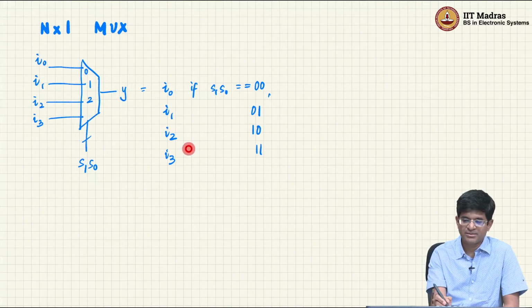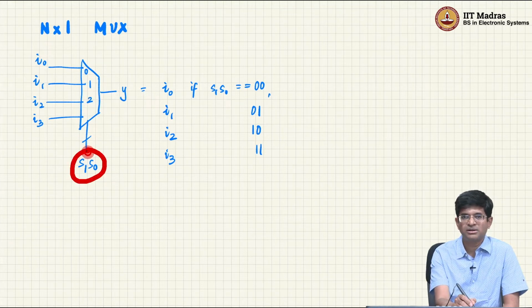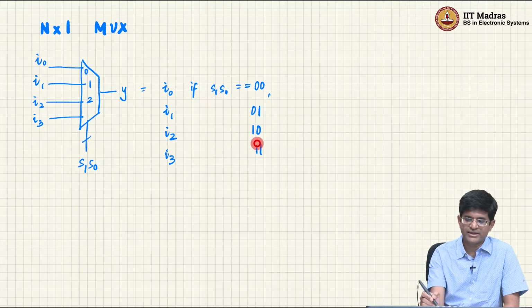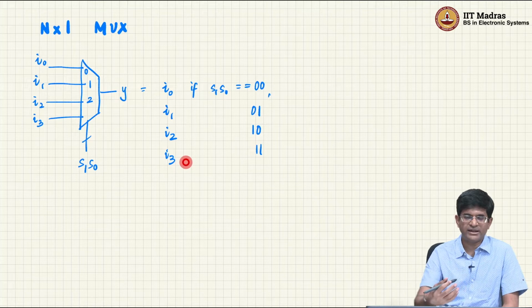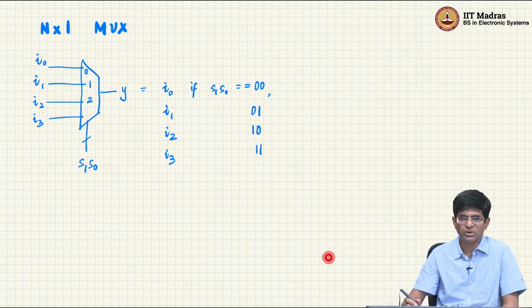So basically this expression out here, if the input was 2, right? Now comes the question, okay, how do I represent 2? And the choice I am making here is to say that, okay, this is going to be a binary number, right? And basically I will treat this S1, S0 as 2 bits and say, okay, 1, 0 basically corresponds to the value 2. And similarly 1, 1 corresponds to the value 3, at which point I3 comes through to the output. So we have a nice compact mental model of how the 4:1 mux works.